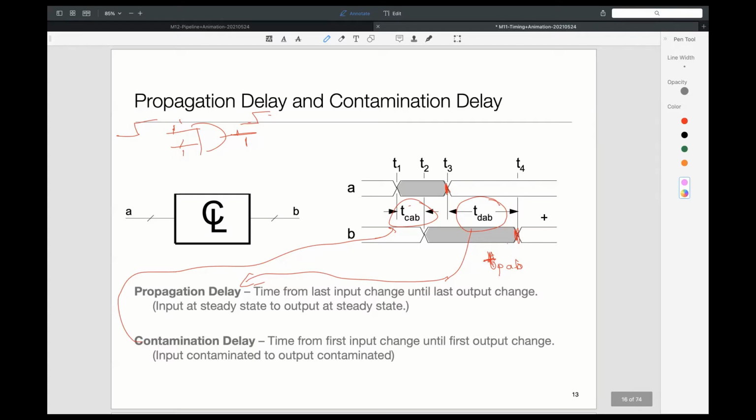If there's a circuit where A takes some 4-bit number, and A happens to be the number 8, then the propagation delay T4 minus T3 may be different than if input A was 6. So minimum would also mean T4 minus T3 across all possible inputs. It's a very misleading concept. Don't worry about it. In this context it will only confuse you. But that's what minimum means: minimum across different conditions. Okay, thank you.